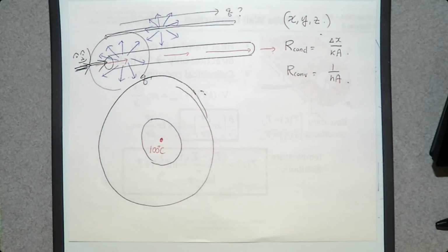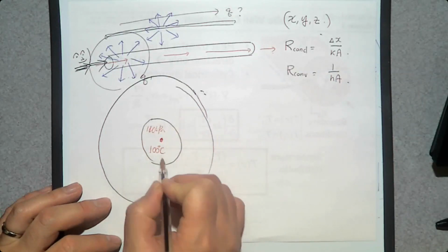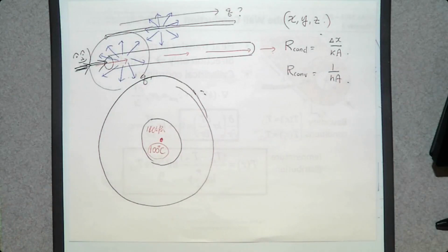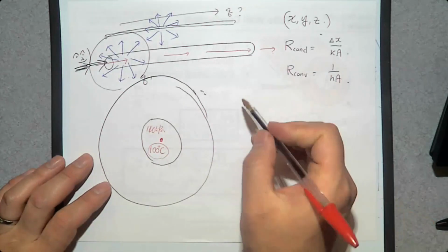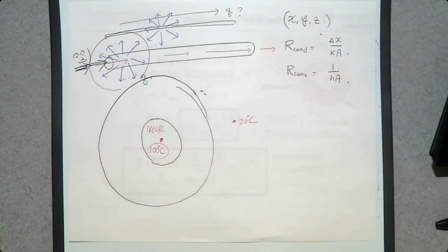Can I say this is near the boiling temperature? I can't, because we studied thermodynamics. Whether it is close to the boiling temperature or not depends on the pressure inside the system. So if I say the pressure is near 100 kilopascal and the temperature is 100 degrees Celsius, now you can say that it's close to the boiling temperature. Anyway, what is the temperature outside? 20 degrees Celsius. Then what is the direction of heat transfer? From this hot water inside to the air outside.